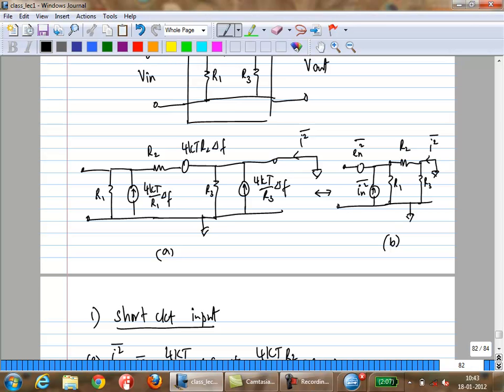At the end of the day, shorting out the output and calculating the current makes things somewhat easy for you, because, for example, when you're calculating, currents coming out from here all directly flow there. That's all. If you calculate in terms of voltage, obviously the currents will be different, and you have to multiply by this impedance. You'll see that it gives you the same values.